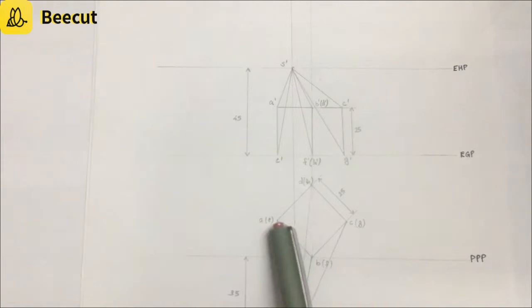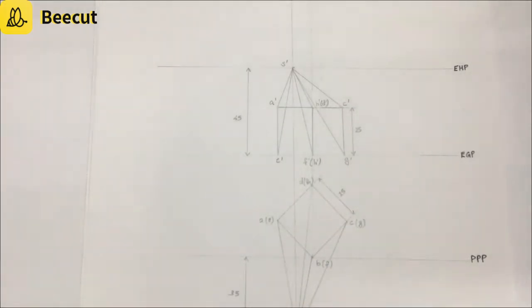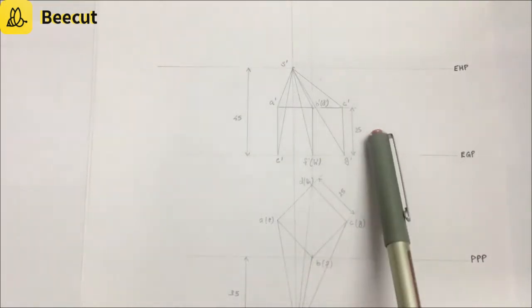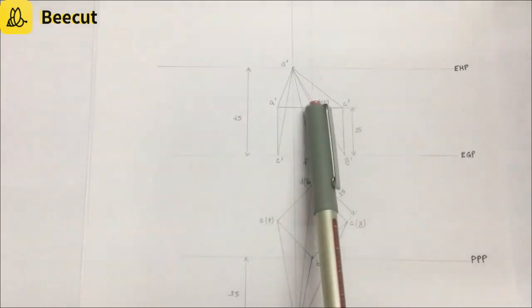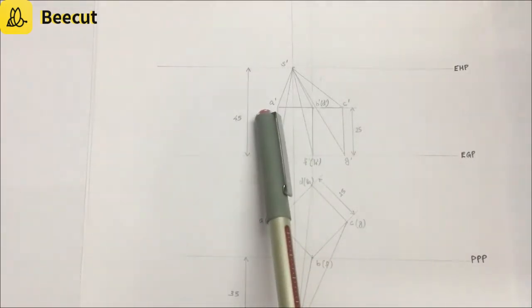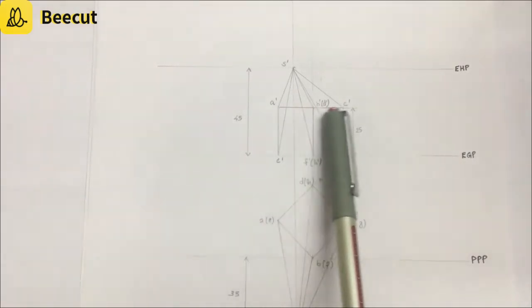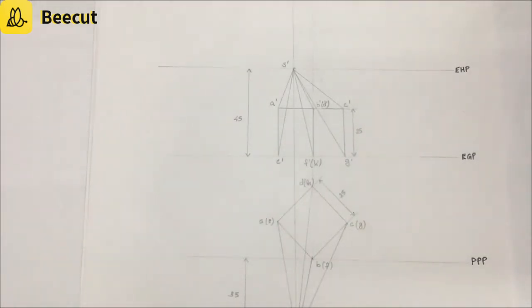On that plane, you have to project from this square, and you have to complete the front view of the cube. And you have to mark the dimensions, 25 here and 25 here. As you have one of the corners here, you will have the center line also visible over here, and you have to mark the ABCD faces over here, and the EFGH faces over here, using the naming stated in the orthographic projections.